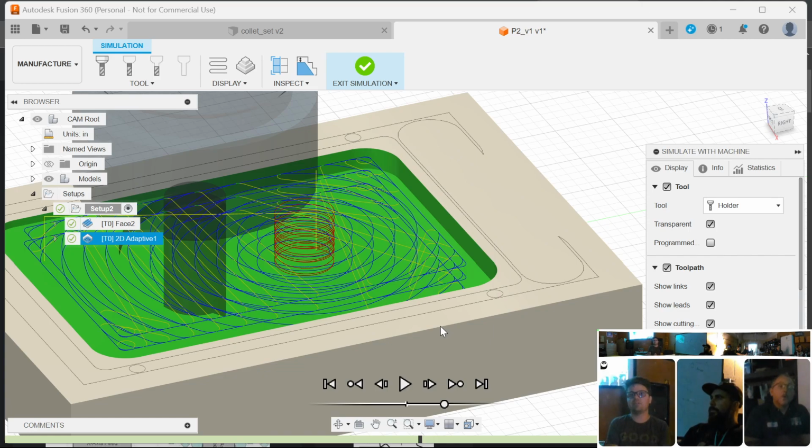Back in the day, CNC machines would do cutter radius compensation in the machine, and the machine would know the radius of the tool, and you would send it paths that were on the edge of where you wanted to cut, and the machine would offset those by the radius of the tool. Everybody gave up on that. Nobody does that anymore, so all of your G-code is driving the center of the tool around, and Fusion 360 has to know the diameter of the tool and is generating the correct tool paths for that diameter of tool. So the machine will have a tool table in it, and the machine knows the length of the tool, and Fusion 360 knows the radius of the tool. Welcome to hell, but that's how it works.